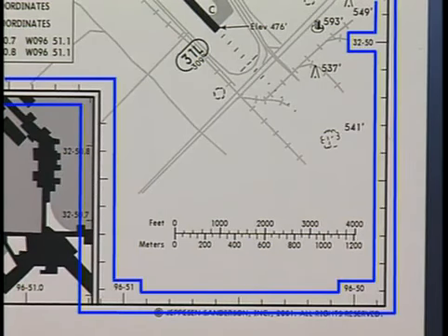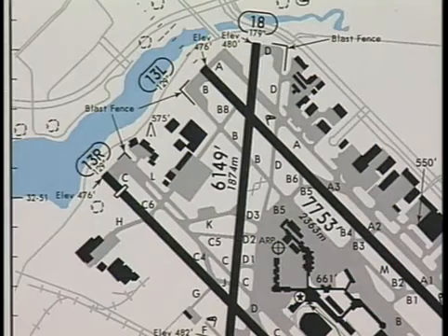Longitude and latitude tick marks are printed along the four sides of the plan view. This helps you determine your exact location if your aircraft is equipped with a lat-long-based navigation system. The airport diagram depicts the layout of runways and taxiways. To avoid confusion, the runways are shown in black, while taxiways and ramp areas are printed in gray.